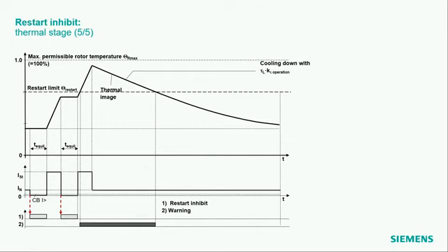Yeah, and then as a difference, here the motor is running. When the motor is running, the restart inhibit function does not give the blocking signal. So from here on, everything is in a safe situation. When I switch off the motor later, I just get again this equilibrium time blocking, if I want that, but nothing more. Then I can start the motor again. So I hope this gave you a little better insight into how this function is working.